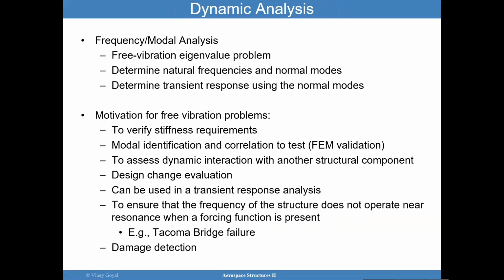Modal analysis allows me to get natural frequencies, and it gives me the mode shapes. And I already discussed what a mode shape is. It's a shape the structure is going to take when it's vibrating at that particular frequency. And the natural frequency is really how many cycles per second that structure is vibrating if it were to vibrate in that motion. And so my end goal is to use this idea to solve transient problems. And I'll demonstrate this a little bit later.